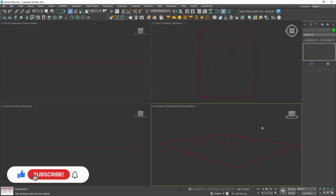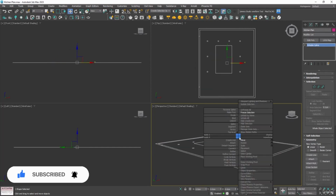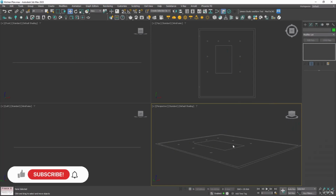Alright, so these are our floor plans, and in this video we're going to take a look at quickly getting this modeled, and you can grab the resources if you want to follow along. Before we do anything, notice we have the potential to accidentally move these floor plans around. So we can right click and Freeze Selected, and then notice we can't actually select our floor plans anymore.